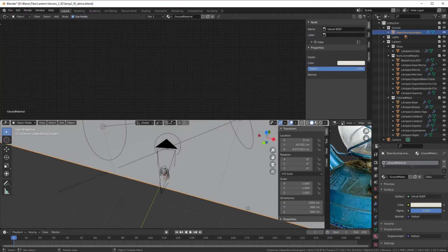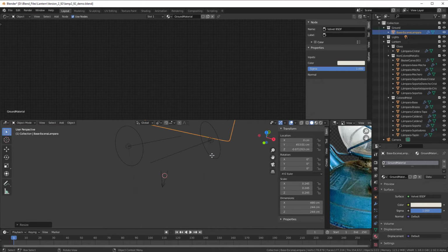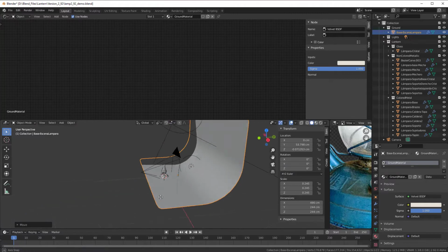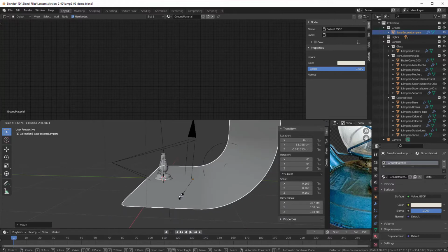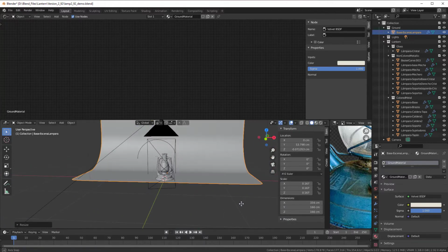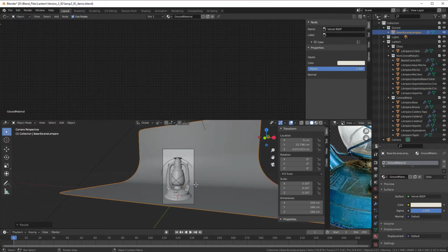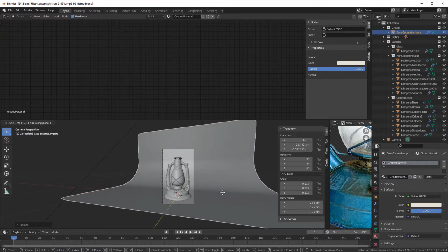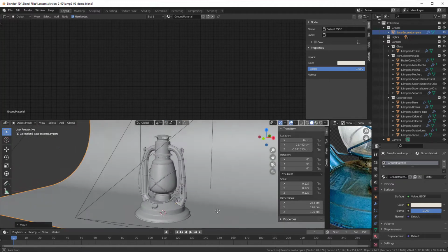So we just select that and press S to scale it down so it's small, and then you can press G, Y to move it a bit. I can go a bit closer, we can scale it even more. So we have it like that, and now it's time to look in the camera to see, and we can scale it like that, and G Y, so we don't destroy anything.